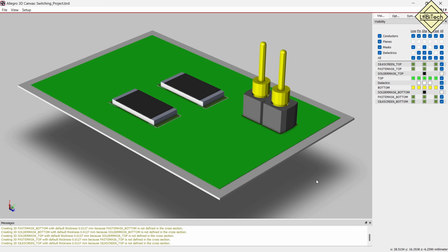So this is the way you can create netlist, and when we come back to PCB board, we will import the netlist. So this is very important while switching. Make sure your symbol pin numbers and pad footprint pin numbers are same, should match it properly. So here in this through hole component, that is PTH component, the pin number 1 is named as 01 in schematic, in symbol as well as in footprint.